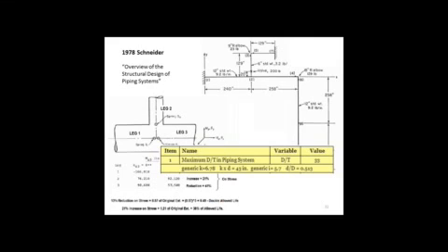If we look at KD, which is the effective length, the flexibility factor times the diameter of the branch if it's the branch side flexibility, or D is the diameter of the run side if it's the run side flexibility. The multiple K times D is 43 inches in this problem. If we go up and look at the piping system branch, we see that the branch has 129 inches of total length before we get to the axial run. So what we're looking at is 1/3 of the length is added by the flexibility factor at the branch connection at the point where the moment's the greatest.